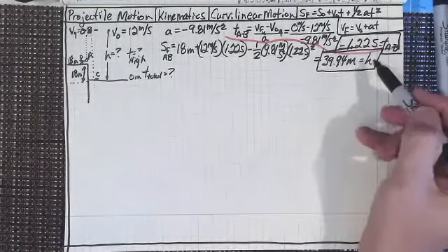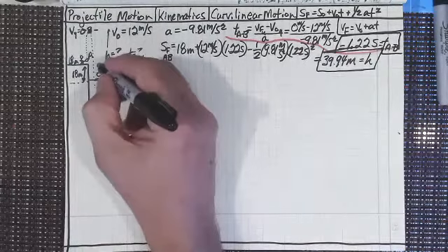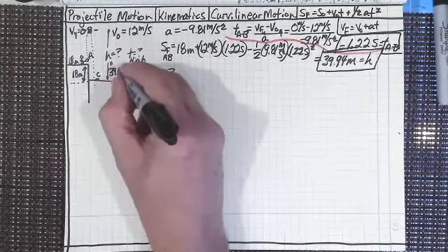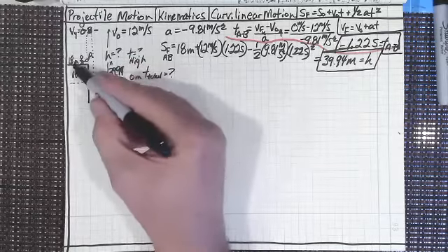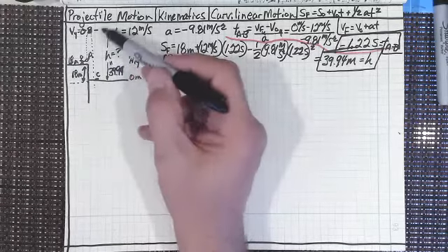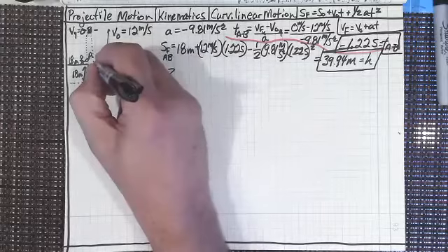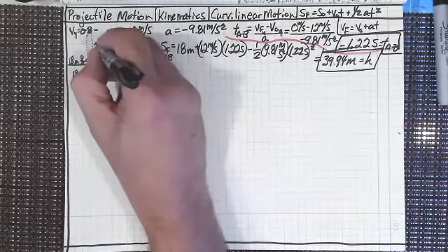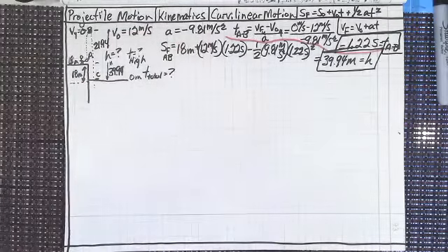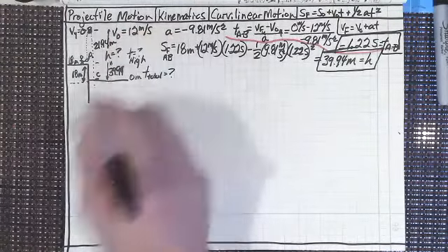We've got the actual height above the datum plane. So this is equal to 39.94, but remember it's got 18 meters already, so it's only 21.94 above. So if I had to look at this distance here, that would be 21.94 meters, right?